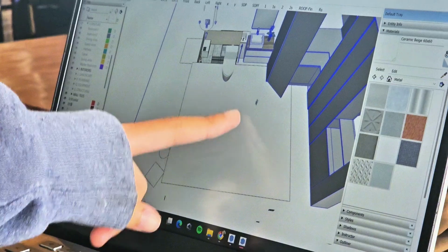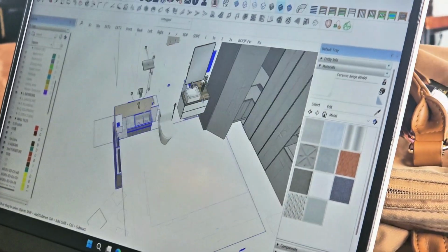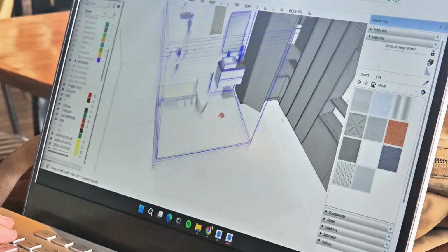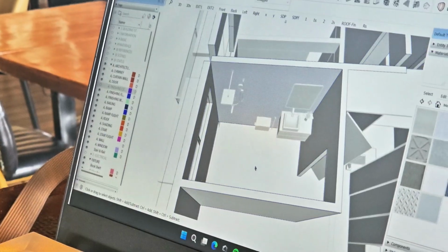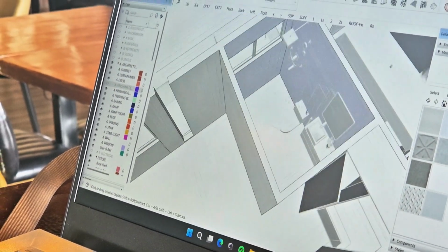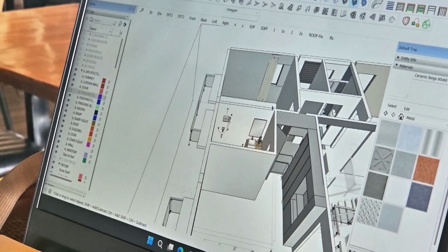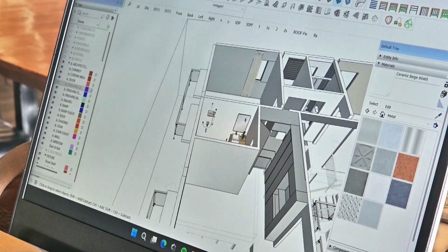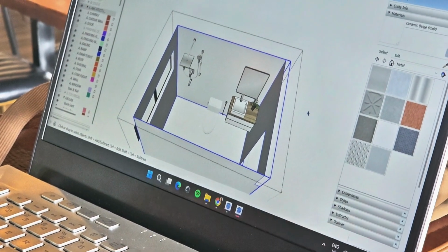For the bathroom, select the whole bathroom, and then name it, because we will put it as bathroom details. The only problem with that one is there are no tiles modeled. So hold down shift and select all the internal walls. Okay, one more. And then paste in place. You remember the shortcut? Then add shift. Now turn that whole group into a component.